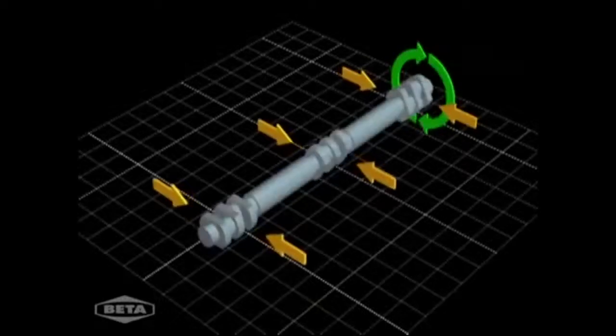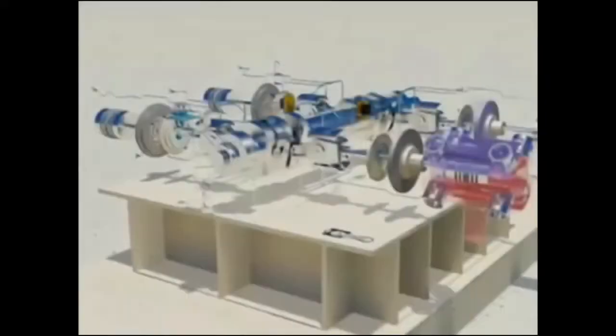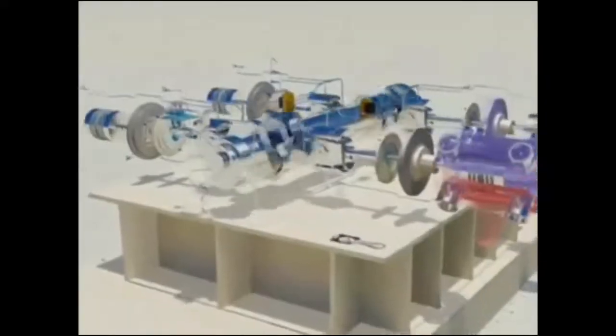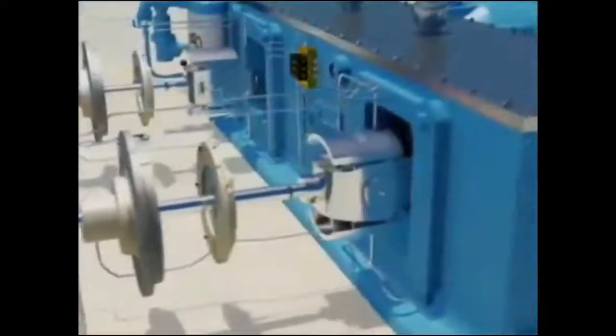The load from each cylinder acts on the crankshaft, resulting in a torque that can cause vibration problems. Each machine will have a unique load profile. A torsional vibration analysis considers how this combined load interacts with the crankshaft, the engine or motor, the coupling, and the resulting stress and vibration on the system.